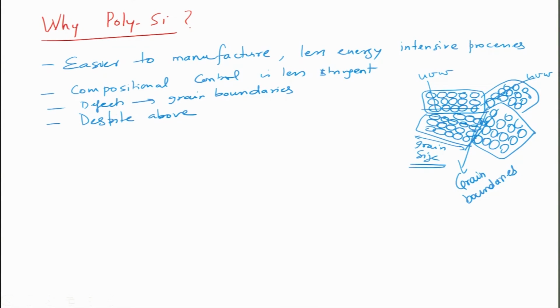In polycrystalline silicon solar cells, generally the grain size is of the order of the thickness of the device or even larger. So they have big grains, they don't have small grains. So grain boundary effect is minimized. So despite our issues, performance is not very bad, is not very poor. So polycrystalline solar cells, as we have seen, have efficiency of nearly 22 to 23% as of today.